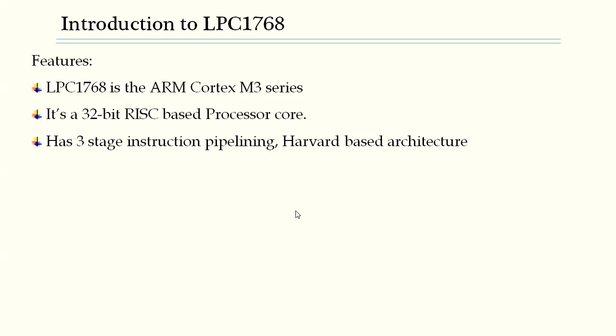Similarly, the memory arrangement defines the type of architecture. If you have a processor memory which is combined, that means the code and the data go into one set of memory itself, with no demarcation saying that the code memory is used only for storing instructions and the data memory only for data. Then that type of architecture, a combined memory architecture, we call the von Neumann.